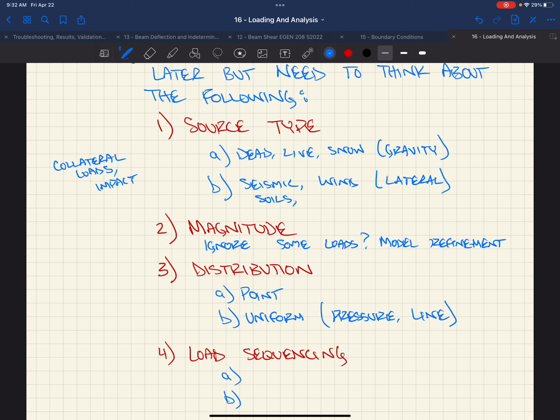If you had something that could distribute the pressure from the wind vertically, you could load, say, plates or areas on the side of that stair tower, and then have it distribute to all of the diaphragms. Or you could do a line load, assuming a distribution between diaphragms. You could come up with a magnitude and run that line load across the entire structure, right?